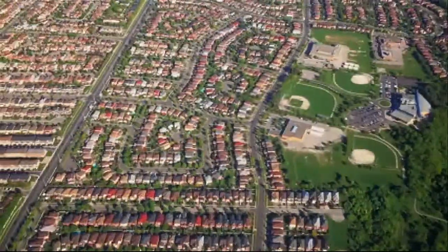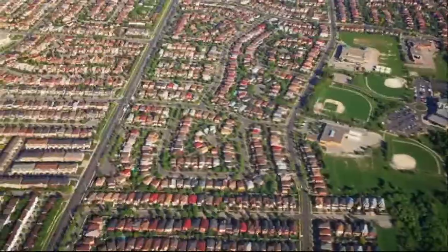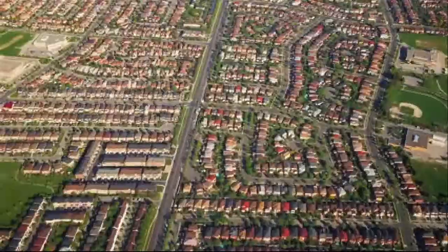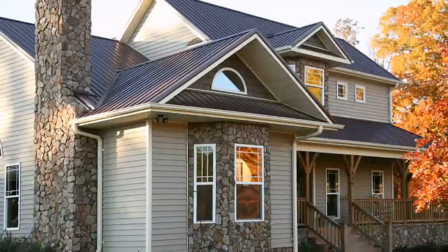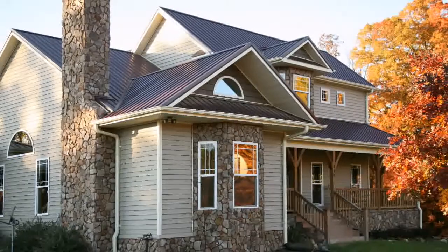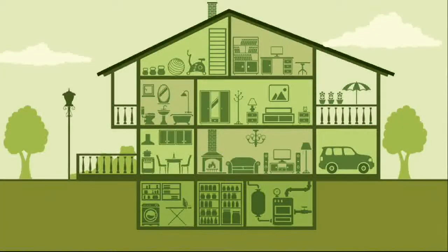In a typical home with one furnace and AC, changing the thermostat settings changes the temperature in every room of the home. To have different areas of the home at different temperatures requires manual or automatic zone control. Zoning means the selective heating or cooling of different areas in a business or home. Unused rooms can be left idle, while occupied areas can be heated or cooled as needed, thus saving energy.